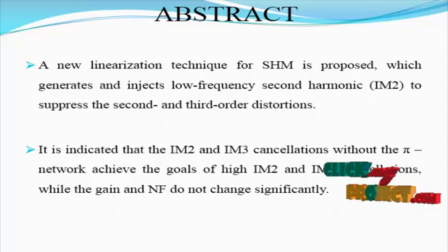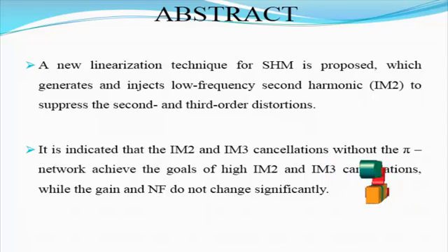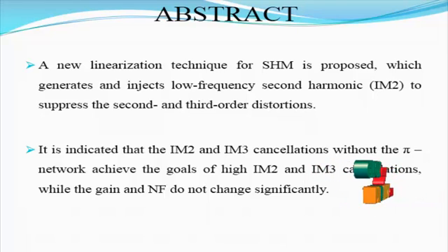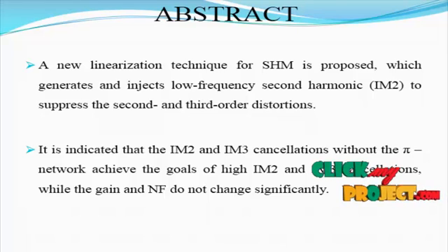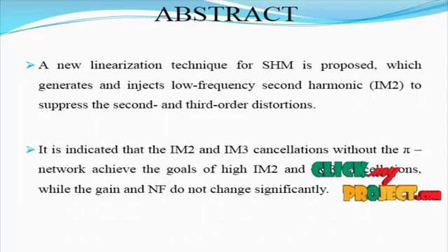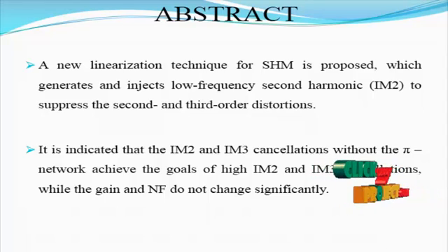distortions. The solution to overcome the self-mixing and the DC offsets is the use of a subharmonic mixer, which uses one harmonic of the LO signal instead of its fundamental tone. In this case, multiplication of the LO signal by itself is prevented. It results in the elimination of the DC offset.